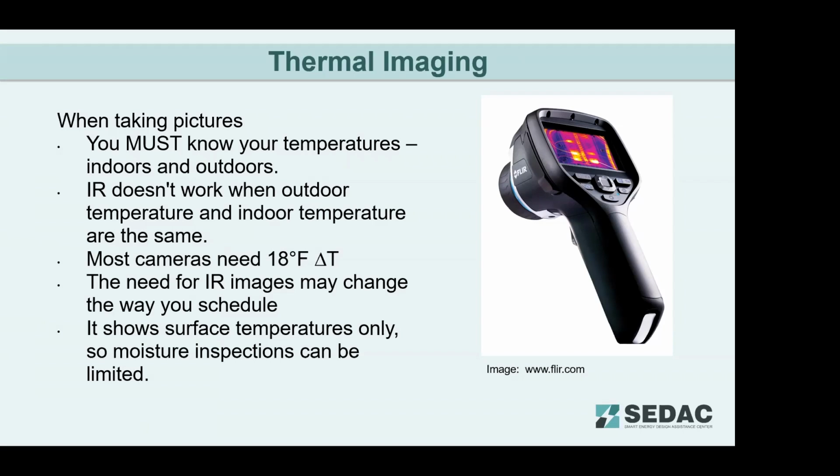The person using that camera must know their temperatures between the indoors and outdoors. I can't take my camera every day of the year into a house and expect to use it. When it is 70 degrees outside and it's 70 degrees inside, I can't use it on the walls. There's not enough temperature difference; the camera's not going to pick it up.